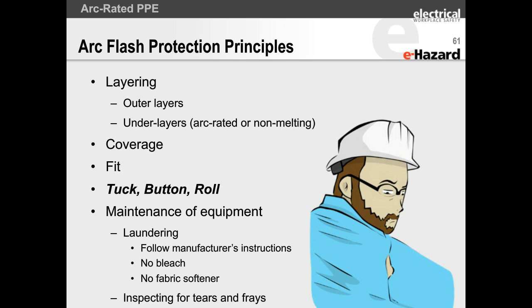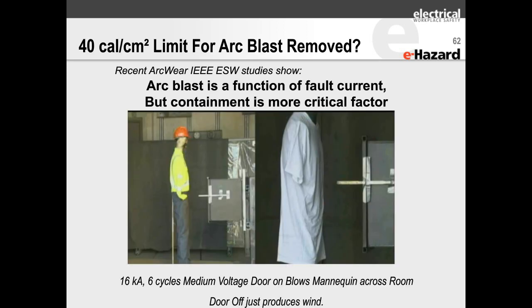Arc blast. This is a part of a paper that we did, and we just recently did another paper. We blew up about 20, 30 different times in this box. In this case, you can see that's a foam mannequin. It's very lightweight. We put a 250-pound mannequin in front of it this time. We can knock that 250-pound mannequin down. Will it kill him? Probably not. We did measure the actual force in newtons. We're going to compare that in this paper.